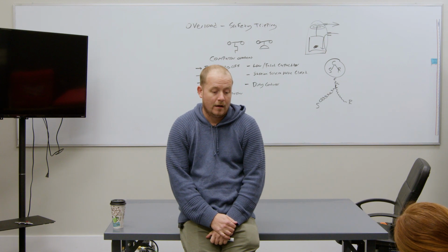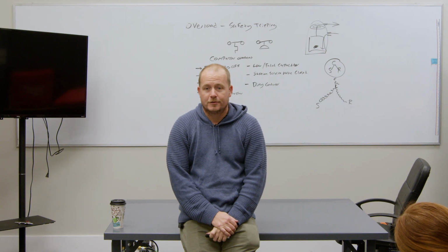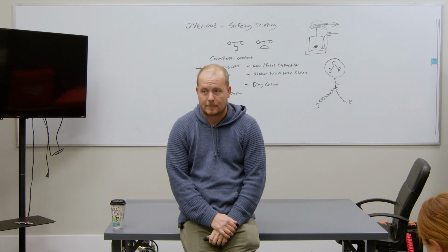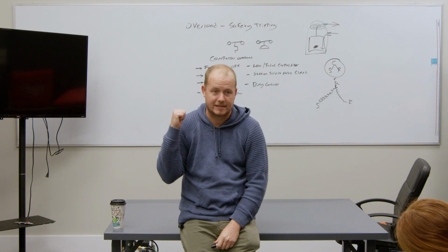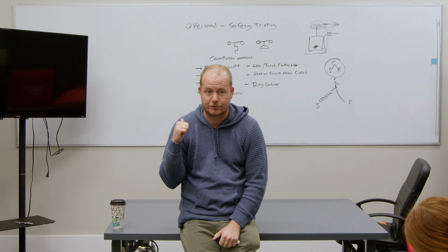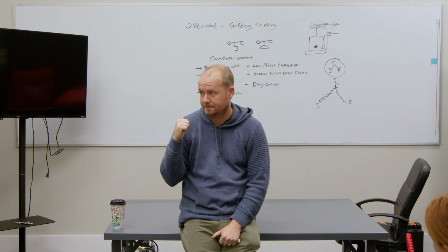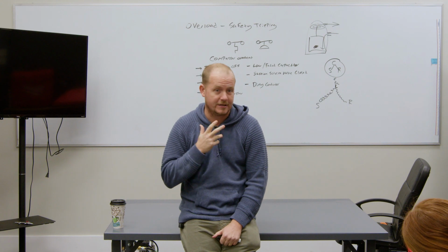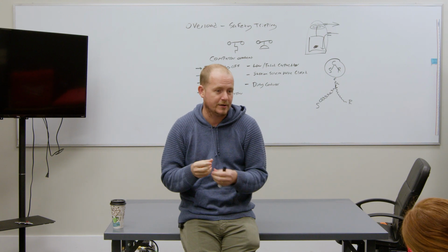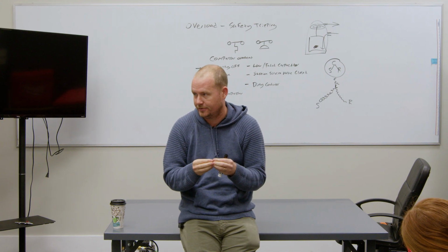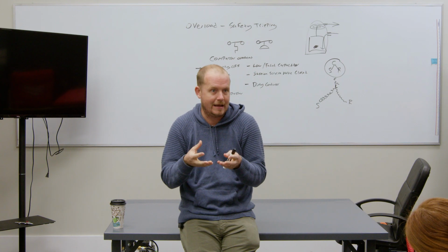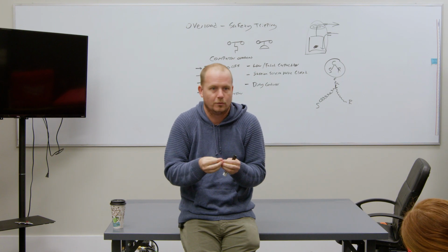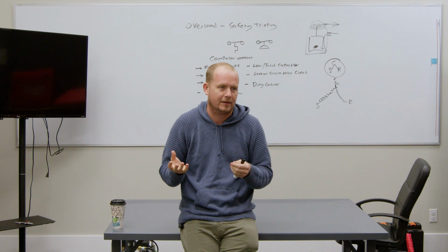All right. This same principle goes for other types of safeties. High pressure switch, most of the same things we just talked about. You got a high pressure switch tripping, they don't just trip by themselves. Got a low pressure switch tripping, they don't just trip by themselves. Loss of charge switch, same thing. Now, if you walk up to a switch and it has physical damage, it's actually damaged in some way, there's cases where pressure switches will leak, for example, and yeah, then they have to be replaced.